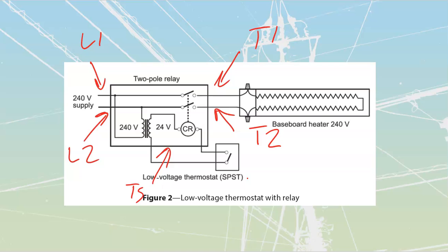I don't know if you've ever been inside of a commercial building. Lots of commercial buildings have low voltage HVAC controls, and a big reason for this is that it can be run all over the place inside of the plenum. That's the hollow space above the T-bar ceiling. If you ever poked your head up inside there, you know that all of your cables and conduits are strapped nice and neat to the surface, but the low voltage wires are just run loosey-goosey all over the place, from place to place. So it's a big benefit for speed and ease of use when you can utilize low voltage wiring, because you don't have the same restrictions. That's why people like to use these.